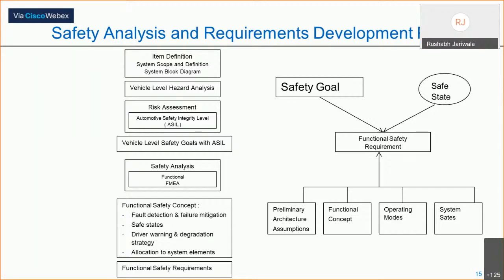if you take the case of the inverter, then when the vehicle is driven, when it is not driven, at high speed, low speed, all of those things, and then understand that if something can fail, how it impacts the vehicle. That is called the hazard analysis, and based on that one identifies the hazards' criticality, and then assigns an ASIL rating for the safety functions.